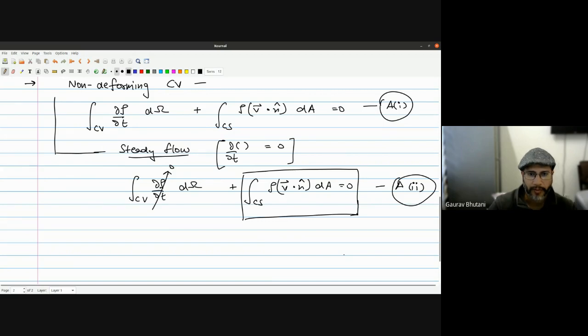So all that is telling us for the conservation of mass situation is that whatever mass is entering is equal to the mass leaving. Because in this case, there is no mass of the molecules changing, that is by definition of the system. And in the control volume, we are saying that the density is not changing with time. So if inside a volume where you have some mass at any given time, the density is not changing, that means whatever is entering is equal to whatever is leaving. Right.